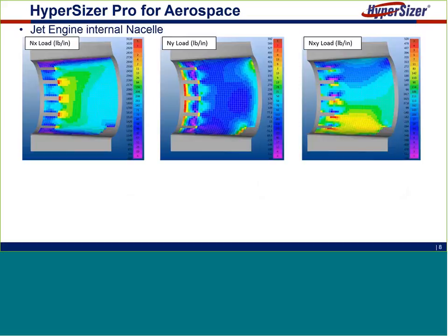Now, as a stress engineer, we would be looking at things such as the displayed membrane NX, NY, and NXY membrane forces, computed. These are the internal shell forces, the stress resultants. And from these plots, along with the customer, we tried to determine the best grouping of elements to assign to a finite element model property. In Nastran, that would be a PCOMP or a PSHELL. And we wanted to know what group of elements should have the same laminate. So what you do is attempt to look at the magnitudes and the gradients of each of these plots to determine the best optimum pattern.